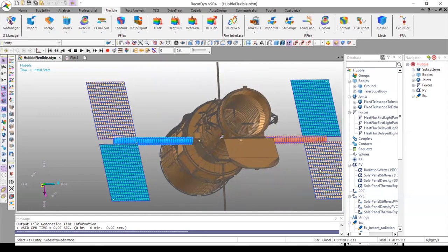And what happens is we have conduction happening, a thermal input on either side of these panels, and it's only applying to one side, right? Basically, solar energy is coming in and it's heating up the material. And what happens with very large spacecraft, and it's becoming more of an issue as we build larger and larger structures in space, is we end up with these thermal shock events. One side of the spacecraft is going to be illuminated while the other is still in shadow. This side is going to start to heat up, and then maybe a few seconds later, this side will start to heat up.